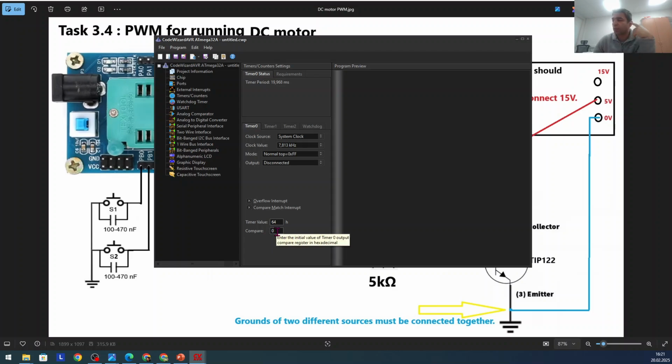we don't have to give right now because we will manipulate it. But here, let's see, I'm giving it like 6. So later you will see where it will go. This is basically OCR1. The number that I'm putting here will go to OCR0, the compare value.